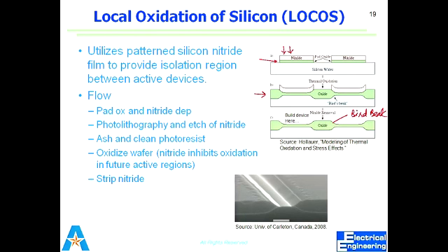Now I want to grow 500 nanometer of oxide in my field oxide, in that pad oxide layer. So when 500 nanometer is grown here, it means there would be this beak as well. Bird's beak would be there. Okay, so bird's beak encroaches inside. That bird's beak means the lateral growth, that would also be 500 nanometer.